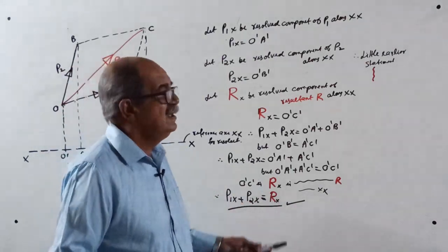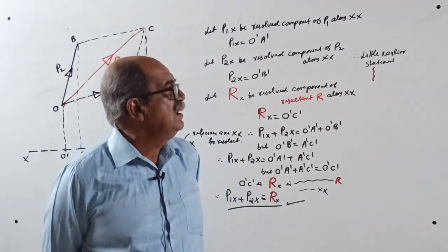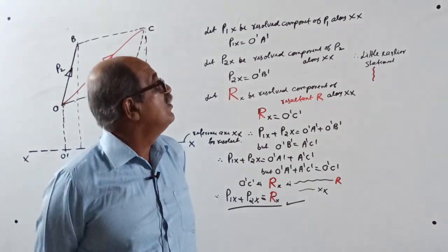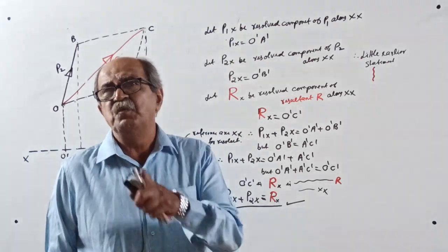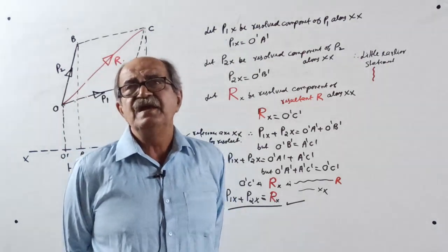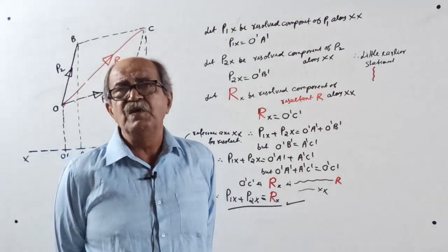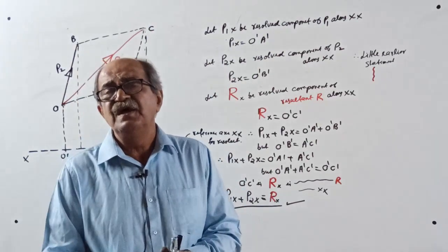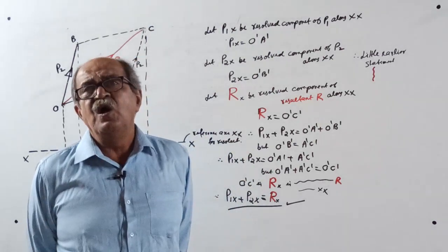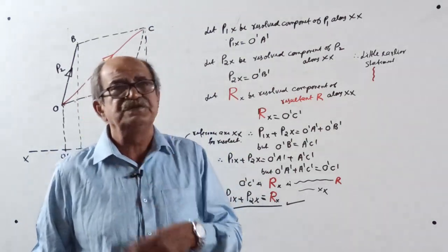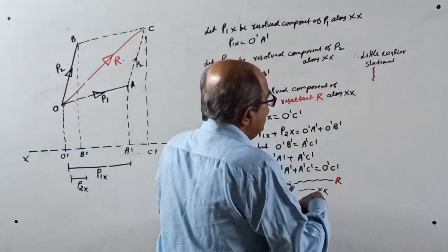Okay, now over. We will meet in the next class, number 15, I think. Yes, most probably 15, I forgot now. Next class we will meet, and remember, the next class is the most critical class. We are starting plenty of numericals: how to find the resultant for a given force system in systematic order. First, a concurrent force system with any number of forces. The law of parallelogram of forces you can apply only for two forces, but now, any number of forces.